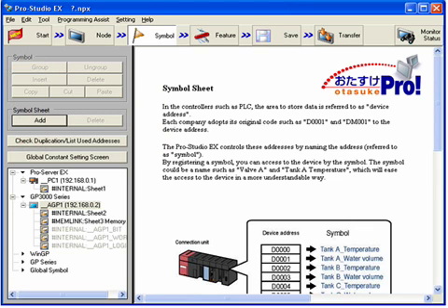We move on to create the participating nodes for the project. We're currently going to enter the symbol addresses that are used within those nodes, and then we can add features in the form of the Swiss Army knife, add features and actions. Then we save the project and transfer it to the participating nodes, and then finally monitor the status online. So that toolbar at the top is not only a useful toolbar, but it also helps you to understand the flow of development for a network project.